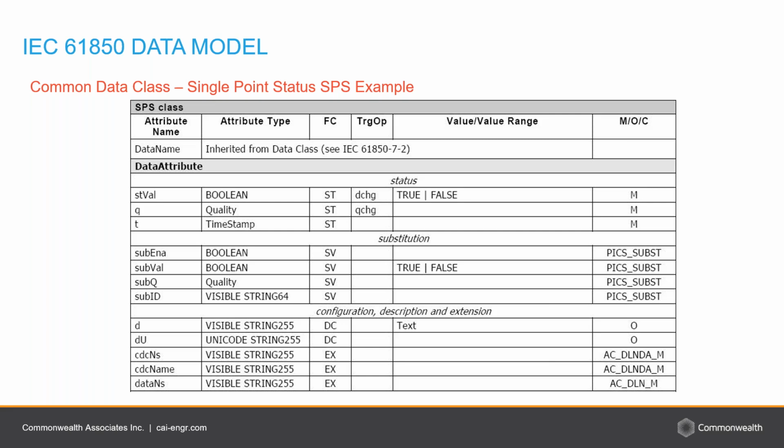So the local operation data element in the circuit breaker logical node will have information about the status value, the quality check, and the timestamp, among other things. Of course, the local operation data element will also have other data from the single point status data class, like enable data or CDC data, which are extended name, functional constraint, and all that. Next slide, please.